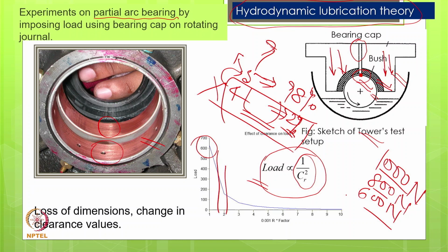This is a continuous process, and finally we need to change the bearing. If it is shifting from 1000 to 950 Newton and we realize something is wrong and take corrective action, quite possibly we may not reach this situation at all, and we can take remedial action well before this kind of situation arises.